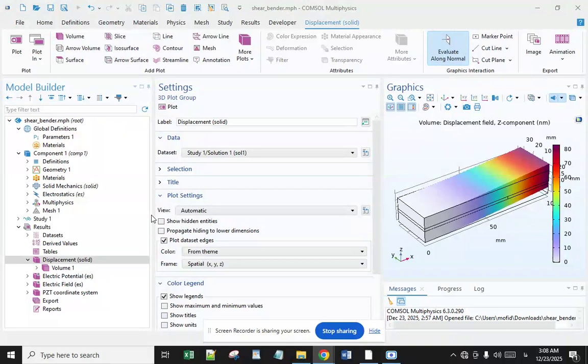Voltage applied to the piezoelectric core has a value of 20 volts, and for the extension actuation mechanism, voltage applied to surface actuator is about 10 volts. As a first analysis, the deflection of both beams for the continuous case, that is, with actuators having the beam's length, was evaluated and compared to the analytical results of researchers.